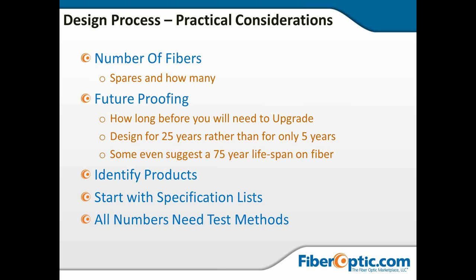These are the questions you want to ask. Understand it is way cheaper to pull larger fiber counts once than it is to go out and pull multiple fiber counts, because the installation cost of the labor is more significant than the cost per meter of the fiber itself.